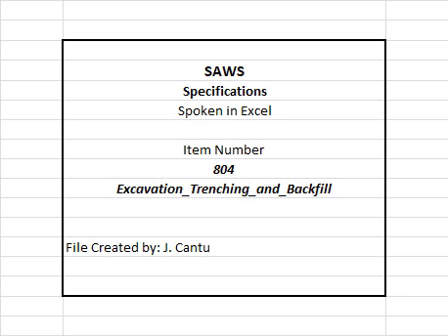4. Submit trench excavation safety program in accordance with requirements of specification item number 550, trench excavation safety protection. 5. Submit record of location of utilities as installed, reference to survey control points. Include A. Locations of utilities encountered or rerouted. B. Give stations, horizontal dimensions, elevations, inverts, and gradients. 6. Submit detailed drawing with plotted utility or obstruction location to SAWS representative.